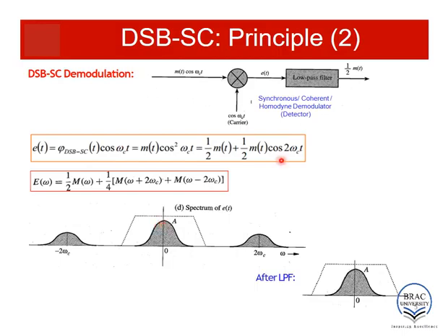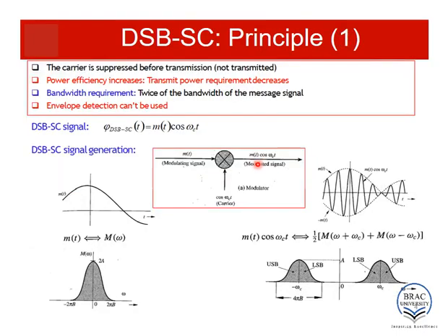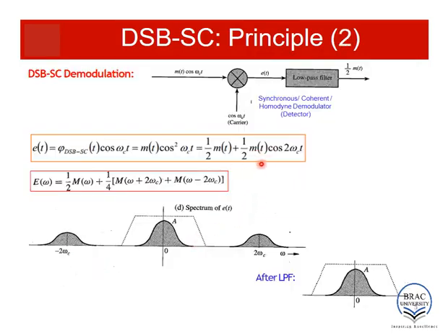Now we know that whenever we multiply a signal with a cos wave, the original message is not only shifted to the positive and negative values of the cos frequency, but also the amplitude of each of the spectrums is half of the original. Now in this case, the message was not m(t), it was half m(t). If in the case of M(ω) the amplitude is 2a, in the case of half M(ω) the amplitude will be a. And as this signal is multiplied by cos 2ωct, the resulting spectrums will have 1/4 of the original message amplitude, that is a/2.